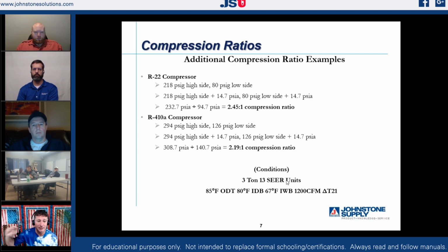If this was a different application and I was talking about a semi-hermetic 3D, 4D, 6D, 8D Copeland compressor, then if I have a compressor that's not operating properly, I can see what my compression ratio is. I can see what the current draw is on my compressor. I could also shut my system down and check the continuity across my windings. And if my motor is good, but my entire system is running at low efficiency, don't I have the opportunity to say, well, maybe I've got a vapor pump problem? Instead of replacing this compressor, how about I tear this apart and put a new valve plate on it and get this thing pumping properly?